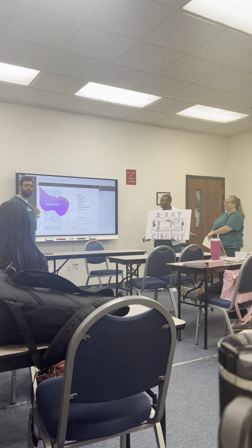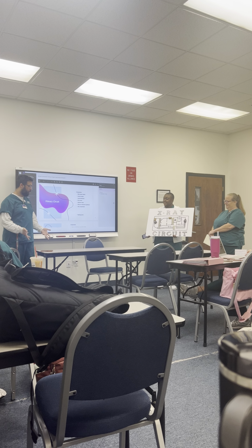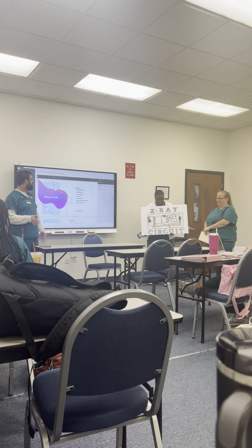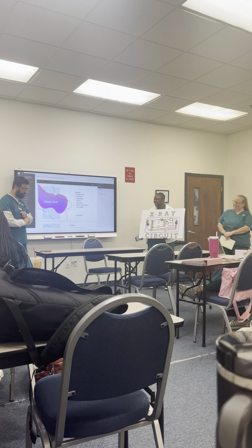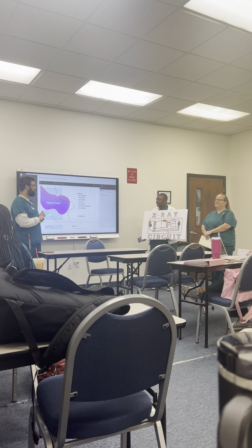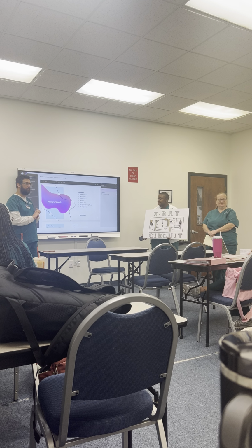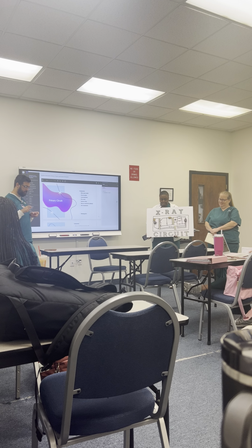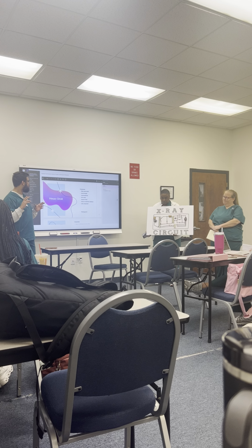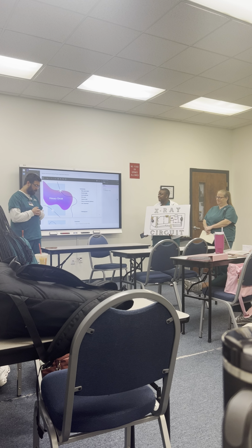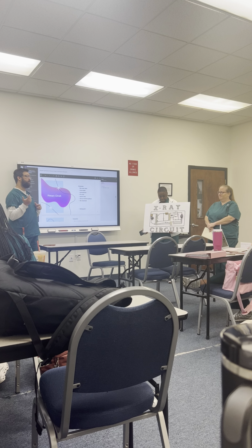Alright, so I have specifically the primary circuit. We have the main power switch, which provides energy to the whole circuit. We have the circuit breaker, which protects itself from itself, and if there was no circuit breaker, it would be a lot more vulnerable to overloads and short circuits. The auto transformer increases the voltage to what the radiographer sets on the KVP selector on the control panel.